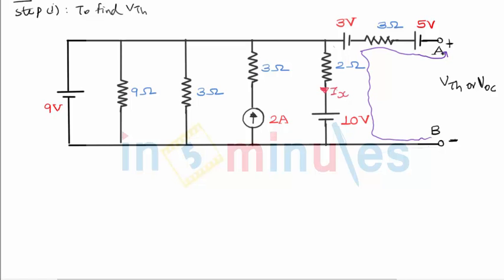Now if you observe carefully, the network that is available to us looks a little big, but it is a very simple network if we plan to apply nodal analysis, because there are only two nodes. The upper entire line will become node number 1 and this bottom line will become node number 2. So if I take this bottom node as the reference node, then I've got just one single node on the top.